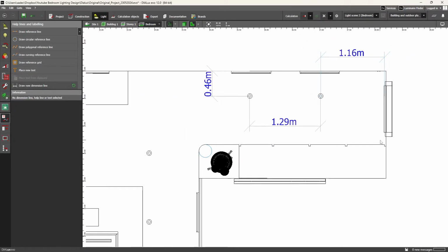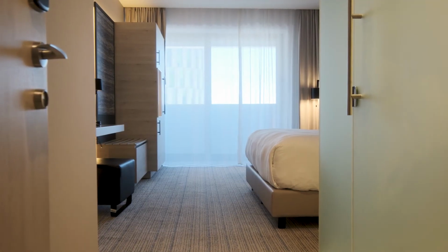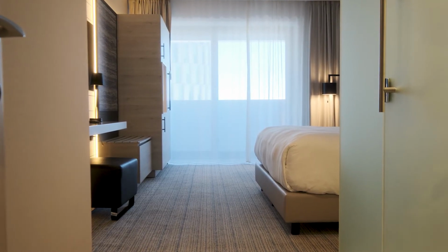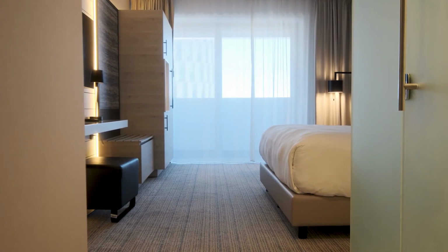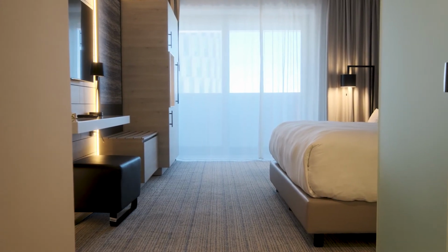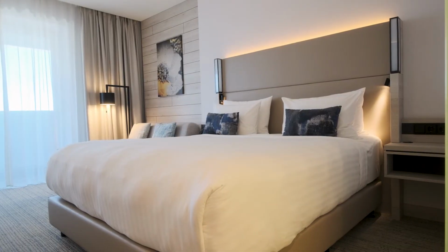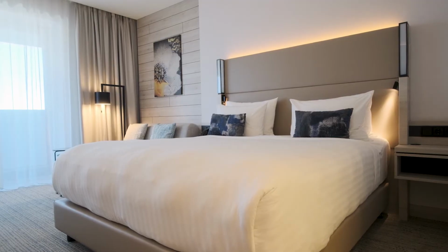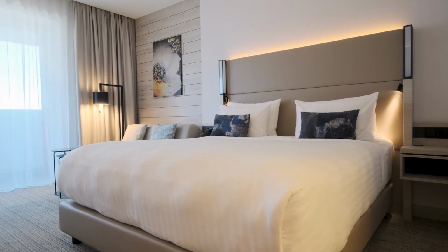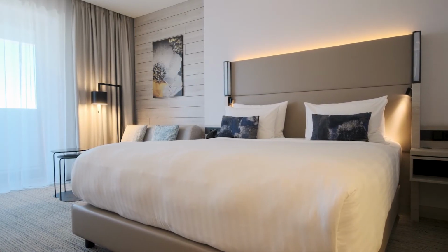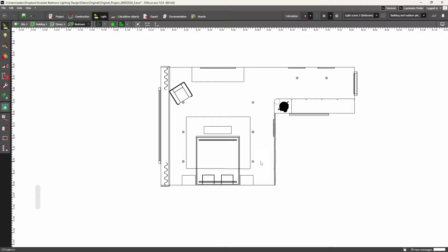Voila. Okay, now, we also need to think of lighting in terms of layers, which enhance our experience and feeling, as naturally the light we perceive outside comes from the sun that reflects and changes on the various surfaces that we have around us. So, the next aspect of lighting design will be what we call task lighting, which are the lighting sources needed to support some specific activities within that room.